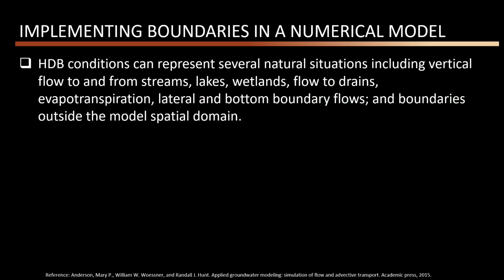So we use the head-dependent boundary condition concept a lot in groundwater modeling, because it can represent different vertical flows. For example, the interaction between the aquifer and streams, the aquifer and lake, wetlands, drains. Evapotranspiration is something that we can use this boundary condition to simulate, and also the lateral or bottom boundary flows in our model.